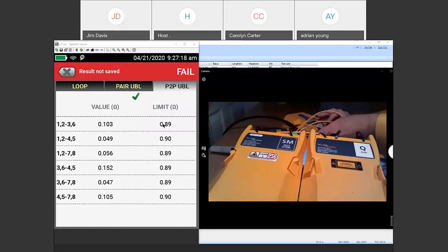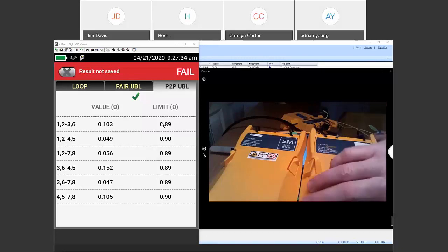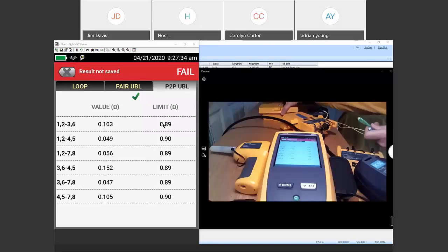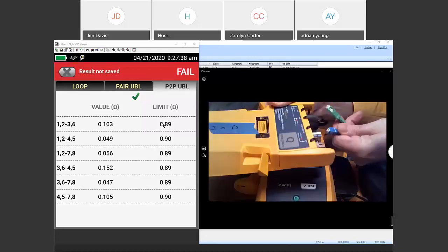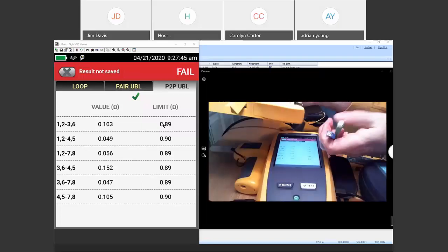Yeah, and my understanding is on the power meter, could you say a little bit about that? Yeah, where we're measuring power, it doesn't matter. So the input port, if you're doing an optical loss test, that can be APC or UPC. It doesn't matter. It's the output that you just need to make sure it matches. And the standards are nice. They do some color matching to help you out as well.